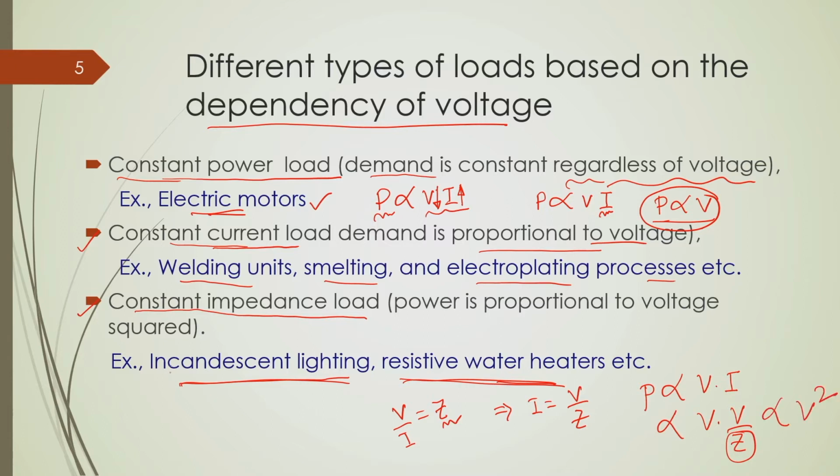So, this type of load demands power proportional to the square of the supply voltage. That is why they are also called voltage dependent loads, where power demand is proportional to the voltage squared. All right. So, this is the classification of loads based upon the dependency on voltage.